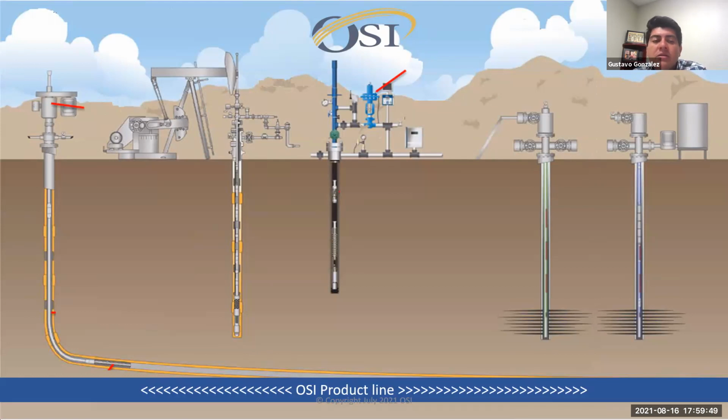Either we plan to separate the sand prior to ingestion into the pump, or we manage it and give some ability to start lifting a portion of that sand, with multiple stages below that artificial lift system. In some cases like gas lift, several operators decide more to start producing the sand. We normally don't see too much damage on the gas lift valve due to sand.